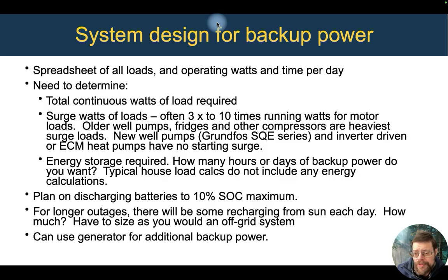Some loads, like refrigerators, it can be more accurate to use a kilowatt meter and see how much energy per day they use, because the power use and the energy use are not coupled well together.